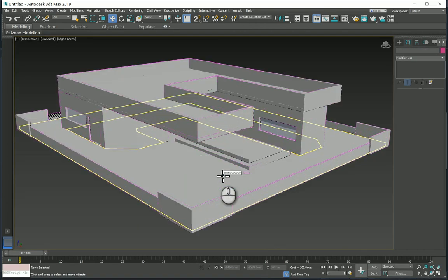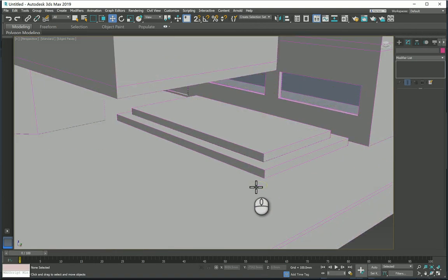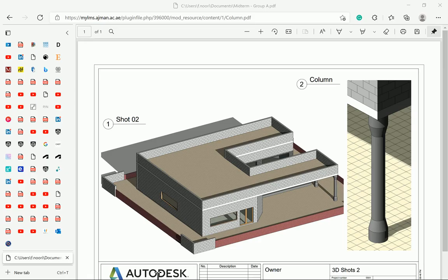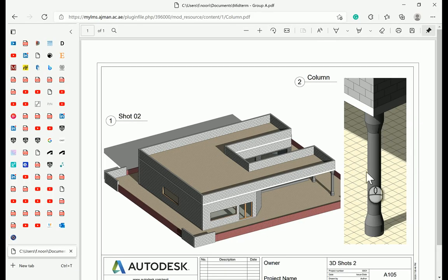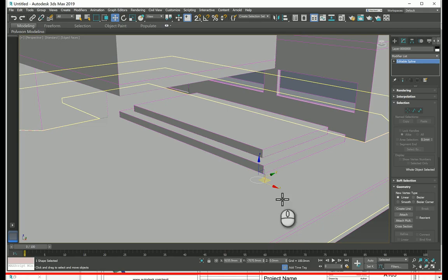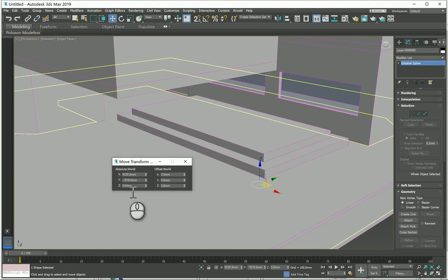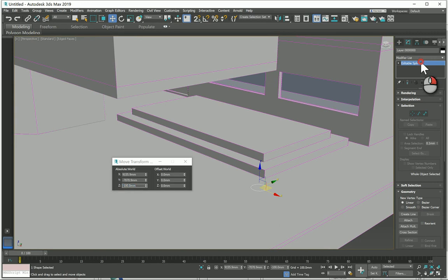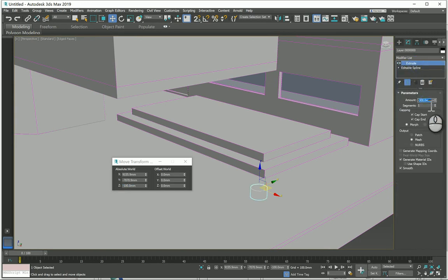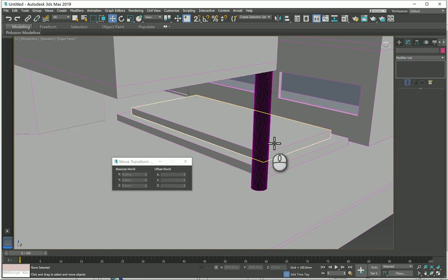All right, so now that's my circle. Now, how do we know where it's located? It's super easy. It's sitting on the walkway, and its top touches the bottom of the slab. So whatever you did with the exterior wall should be applied for it. I'm just going to give an extrude here for the sake of knowing where it should be located. So that's a -100, and the base should be 3650. So this is how it should look.